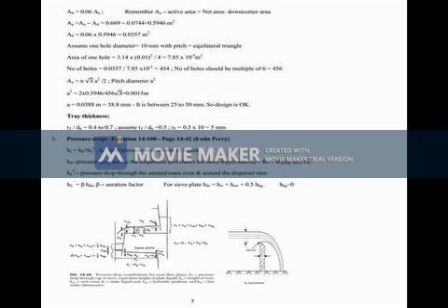First, mark the point at the bottom of the tower. The bottom of the tower will have the maximum amount of gas coming, so the coordinates are xn and yn plus 1. Yn plus 1 is known, but xn is not known. Then at the top of the tower, the coordinates are x0 and y1. x0 is known and y1 is also known because you have already found it. x0 is equal to 0. Xn is not known, yn plus 1 is known: yn plus 1 is equal to 0.06.